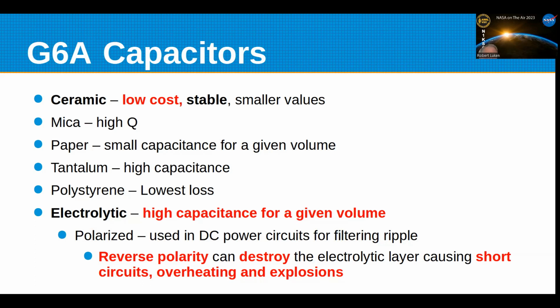And don't touch them until you've shorted them out, because they'll hold a charge for a long time and kick your butt. Especially in a tube transmitter with the electrolytics, where you're looking at several hundred volts. Or in an old television set.